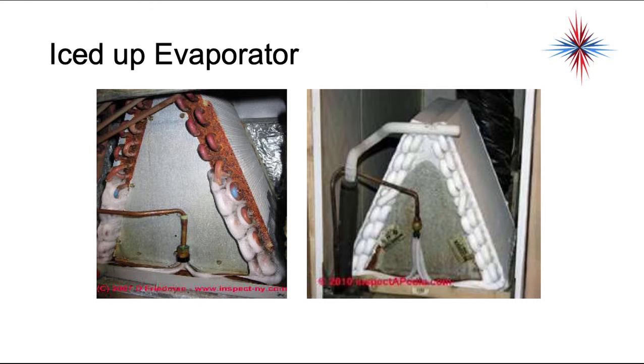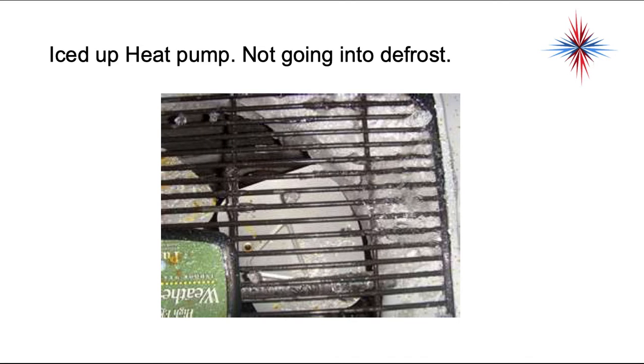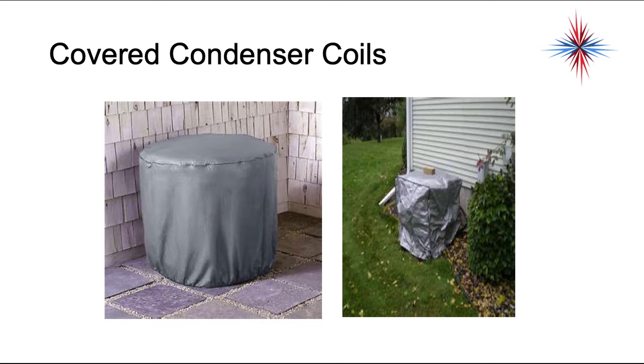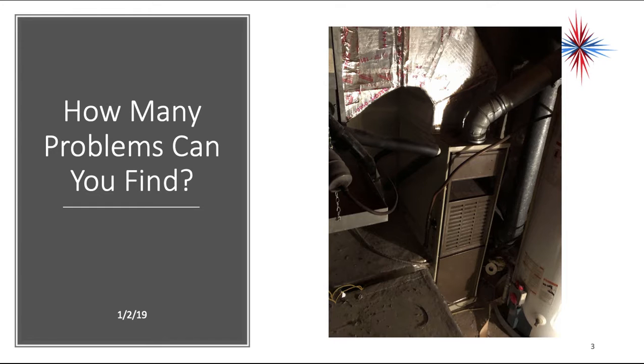Iced up evaporators tell you there's not enough airflow for the most part. Okay, could lead to a refrigeration side problem, but most often it's not enough airflow. Okay, we're going to basically skip over this one, but again, iced heat pump, it's not going in defrost. I'm going to skip that. Look out for issues. Again, it's airflow, but most often it happens in the spring in the cooler climates. Condenser coils are covered.